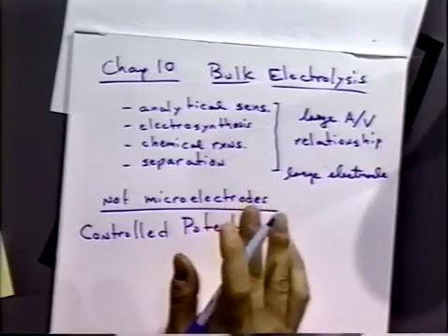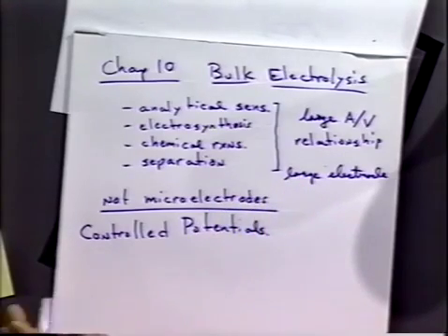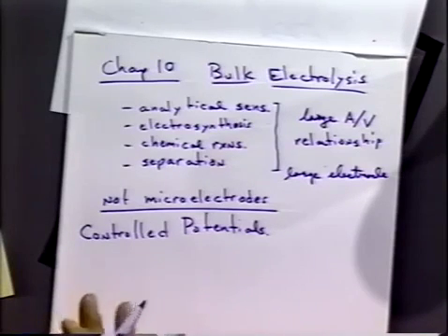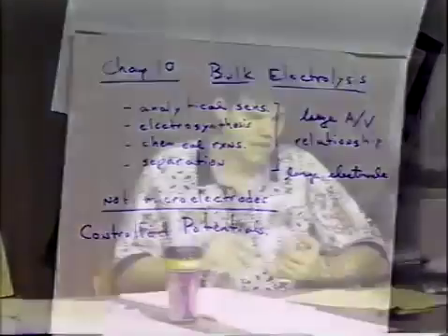Now, a lot of times the difference between these larger bulk electrolytic processes and the analytical processes is that we often have to be much more careful about cell designs and layouts. Because the currents are larger, we have more IR drop possibilities. We have problems with maybe solution heating. We have problems with using perhaps larger voltages and larger currents, which means safety problems. We don't want to electrocute ourselves when we're doing these things. And so we want to be very careful about the cell.